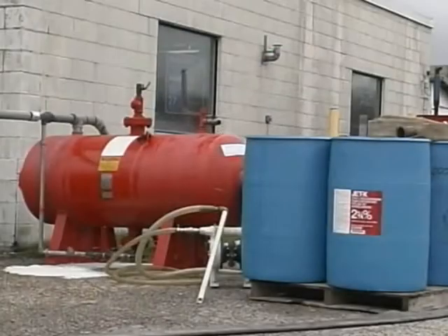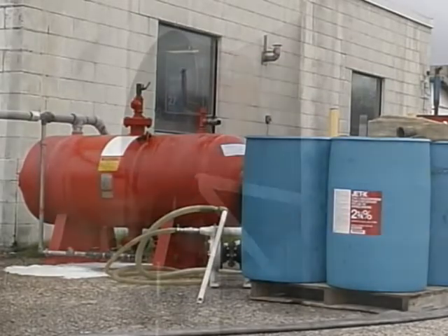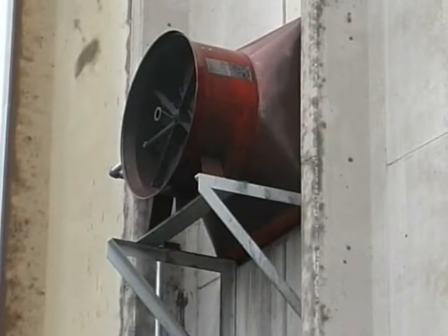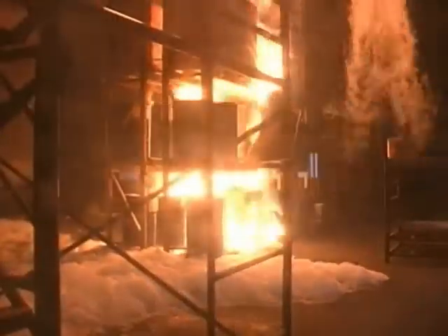The test required 2 JetX 15A high-expansion generators with a total foam output of approximately 35,000 cubic feet per minute, based on an inlet pressure of 75 psi and using outside air. The objective was to have total product submergence in less than 2 minutes. Because of the dangers of running fuel fires, this is actually 1 minute lower than the standard requires.